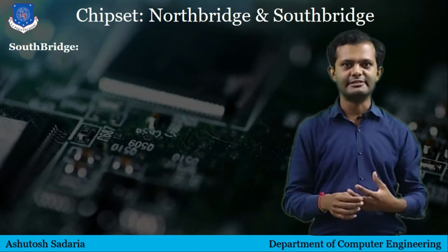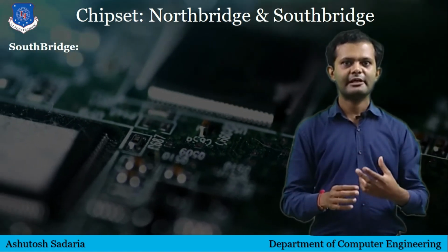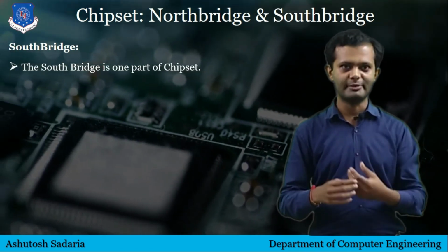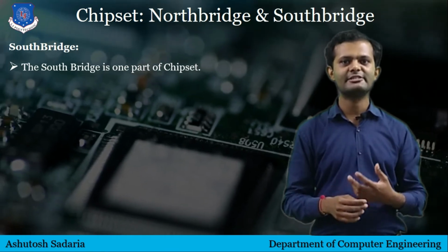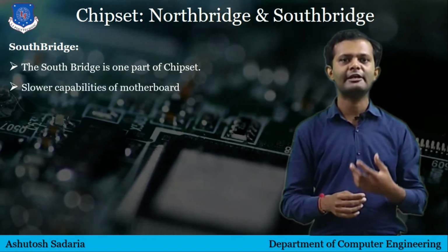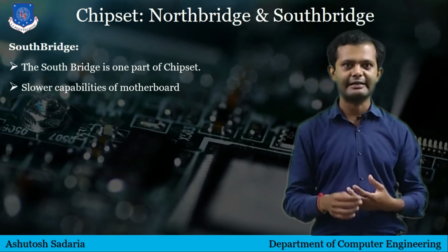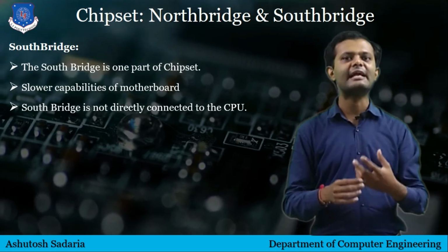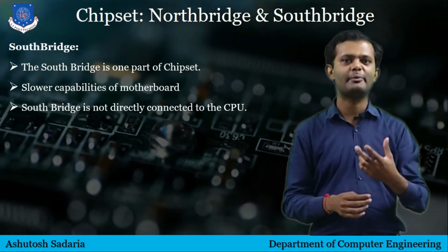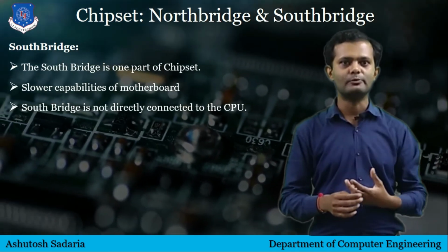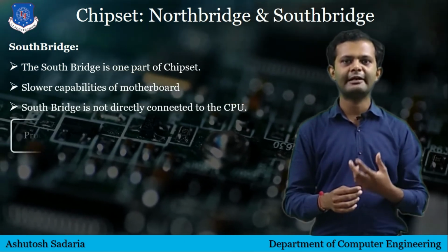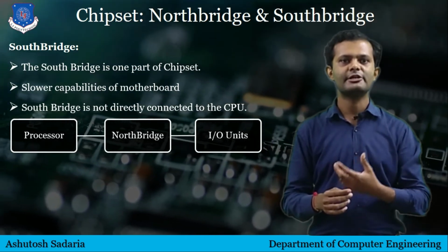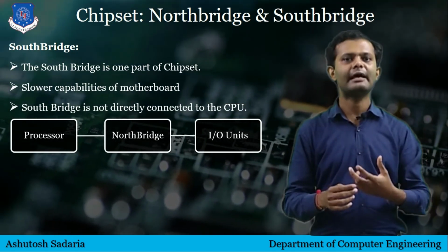The next is Southbridge. Southbridge is one of the chips in the core logic chipset on the personal computer motherboard, the other being the Northbridge. The Southbridge typically implements the slower capabilities of the motherboard in a Northbridge-Southbridge chipset computer architecture. The Southbridge can usually be distinguished from Northbridge by not being directly connected to the CPU; rather, Northbridge ties the Southbridge to the CPU. Through the use of controlled integrated channel circuitry, the Northbridge can directly link signals from I/O units to the CPU for data control and access.